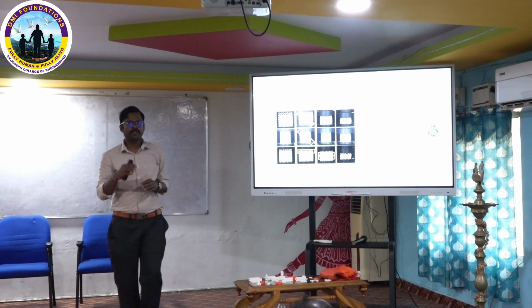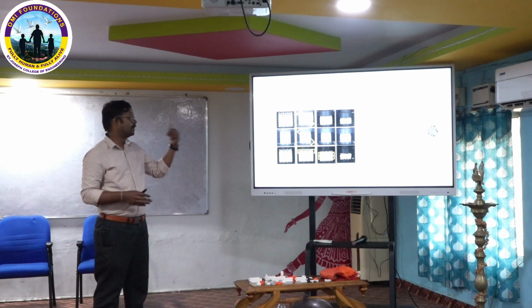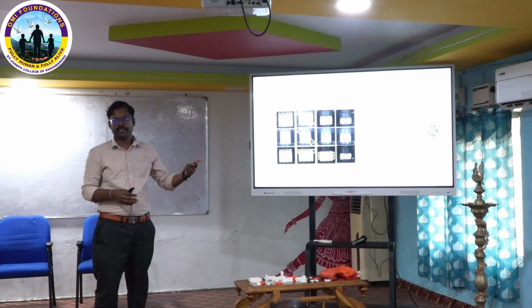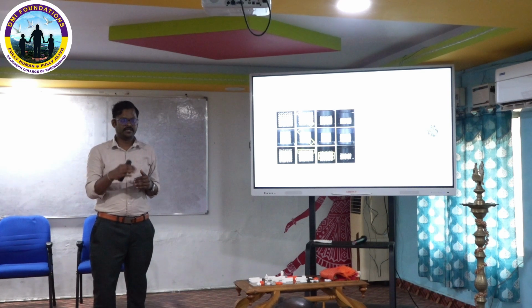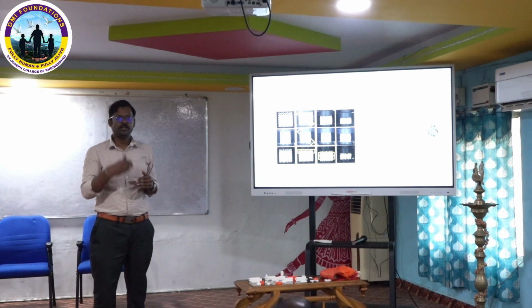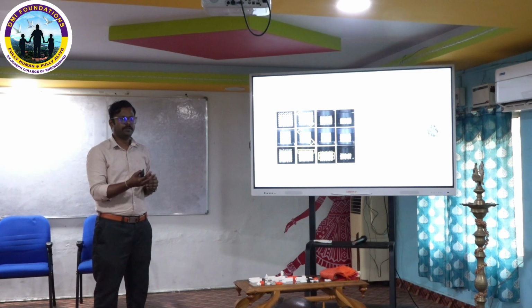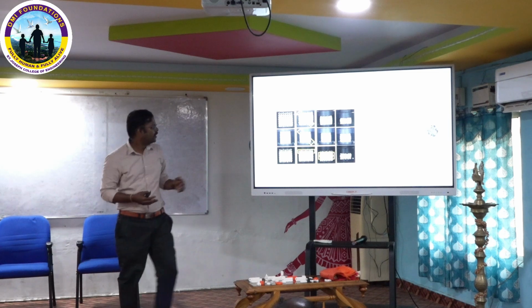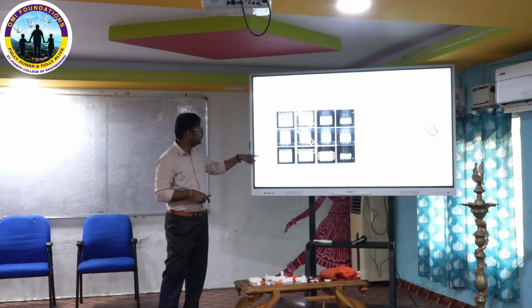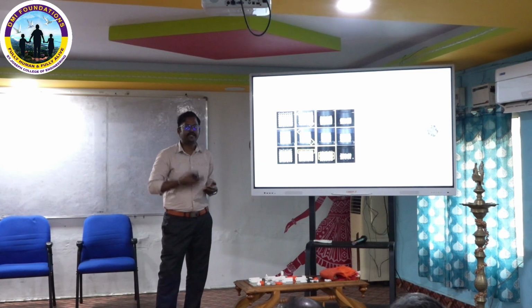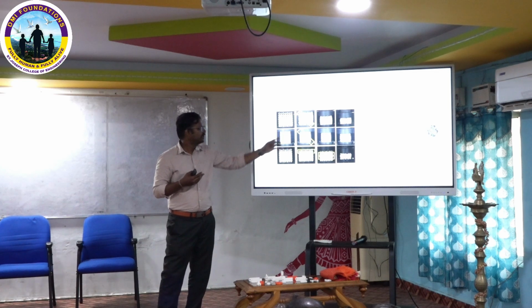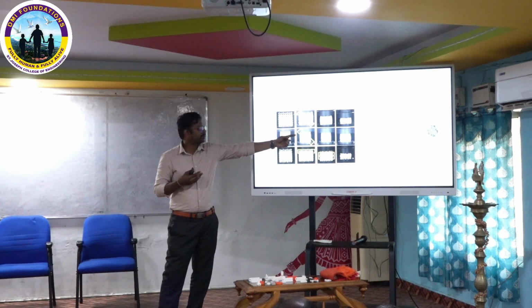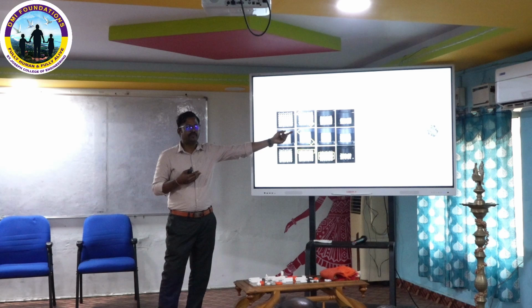It will be suitable for energy absorption applications. Simple cubic structures have higher stiffness, so they will be suitable for more strength-oriented applications. But I also observed that for 30%, when density increased compared to 10 and 20, it deformed as a progressive failure, and the same thing is expected on the graph.